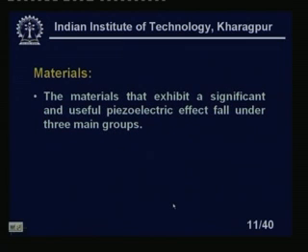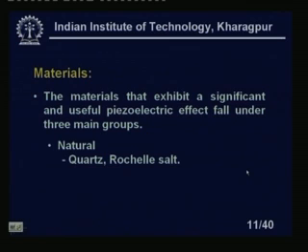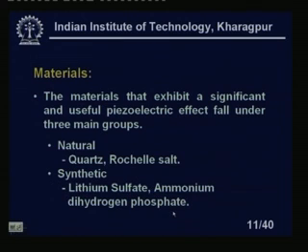The materials that exhibit a significant and useful piezoelectric effect fall under three main groups. One is natural: quartz and Rochelle salt are the two. Quartz is very commonly used and Rochelle salt is also used. Then we have synthetic: lithium sulfate and ammonium dihydrogen phosphate. These two synthetic materials also have the property of the piezoelectric effect. That means, if you apply pressure, a voltage will be developed. If you apply a voltage, a pressure or force will be developed across the plates.